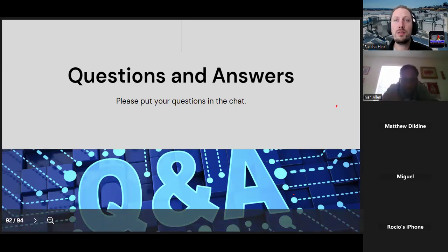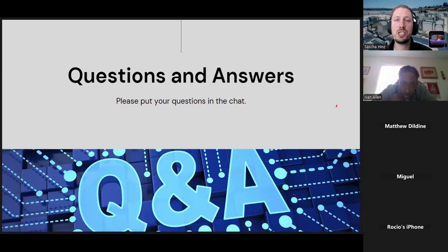One tip I want to leave you with in terms of troubleshooting in general is know the sequence of operation of your equipment. It sounds very fundamental, and part of that is also read the manual. In the beginning, at least for me, manuals were very daunting and I didn't really want to read them. But every manual has a sequence of operation. It's usually a page or two out of the manual. Just go to the sequence of operation page specifically and get familiar with it for your equipment.